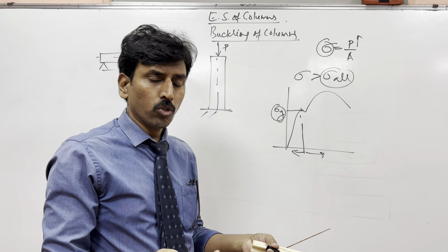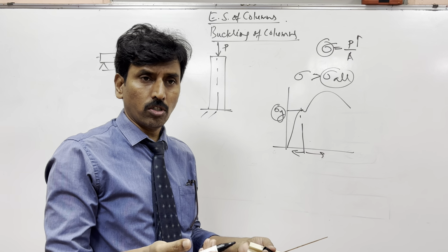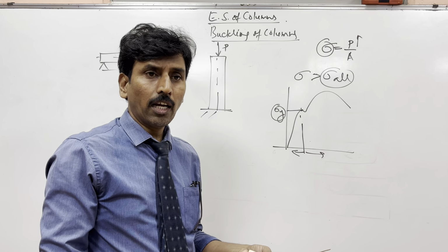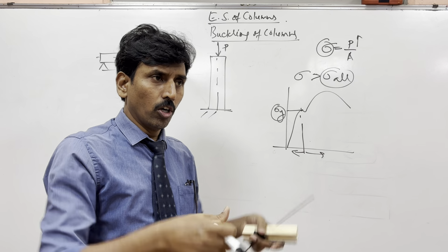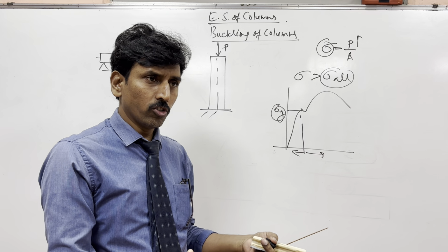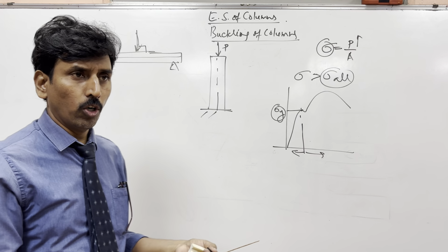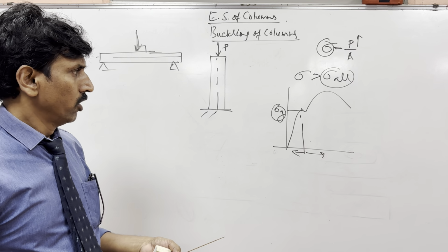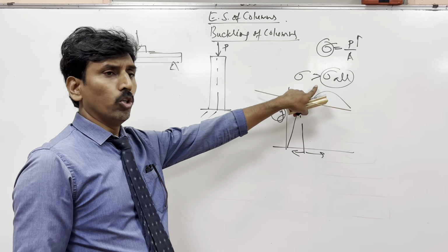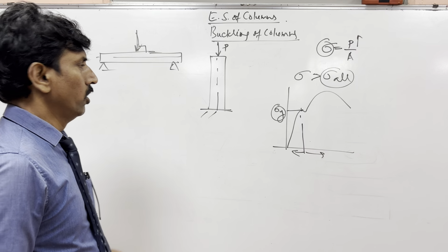If a component's shape has changed, will you buy it? A handle lever, a brake lever, the footrest or any handlebar, if it has changed shape, it has already taken load beyond its capacity and failed. So you need to replace it. Usually you don't go beyond it.